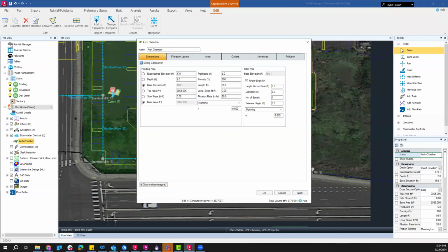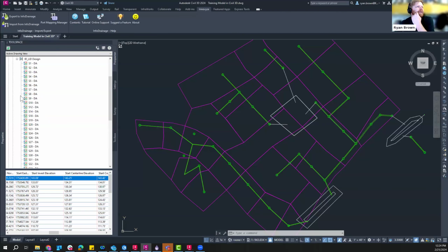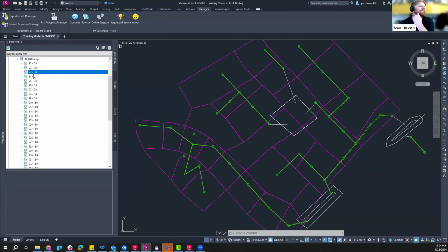Can you bring in the watersheds that are connected to those inlets from Civil 3D? Yeah, so if you have subcatchments laid out here, I've got a bunch of these purple outlines. I know there are tools in here like water trace and water drop trace. You could certainly draw those out into these catchments, and then once you export that to InfoDrainage, it will. So these are actual Civil 3D catchments, not parcels or something? Yeah, correct, exactly.